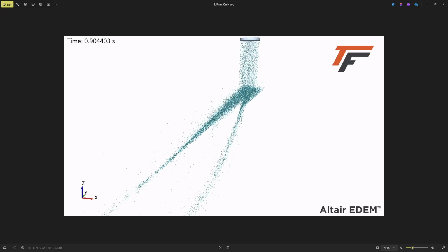There's no centrifugal bias on this spreader. And what that means is if you have a high-speed spreader, meaning a fan type spreader that's really spinning at a high RPM, what those spreaders tend to do is push the larger particles out to the walls because they have more inertia.